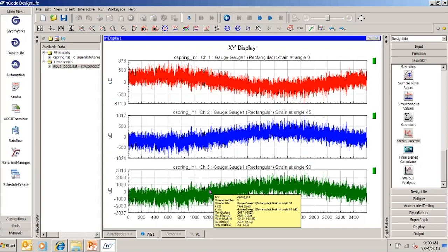And again, these were computed from the superposition of the static stresses from the individual unit load cases being modified by the input load histories. So leg 1 is really the combination of the strains in that direction from load case 1, load case 2, load case 3, each one of those scaled by their appropriate load histories.